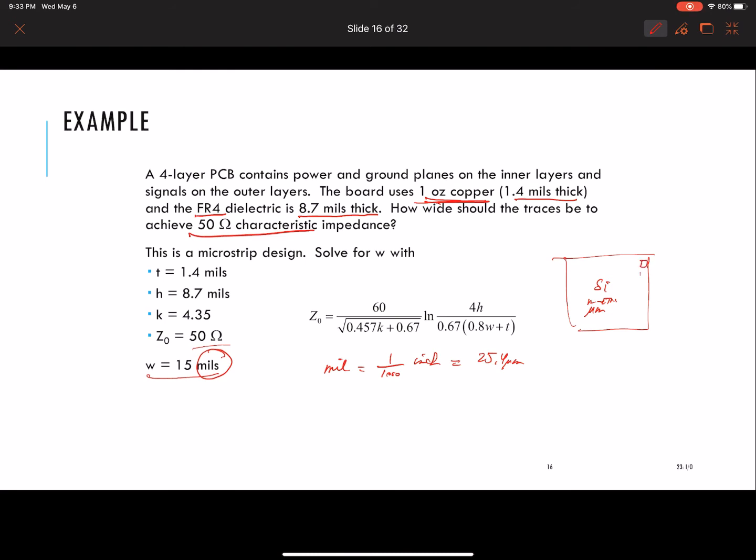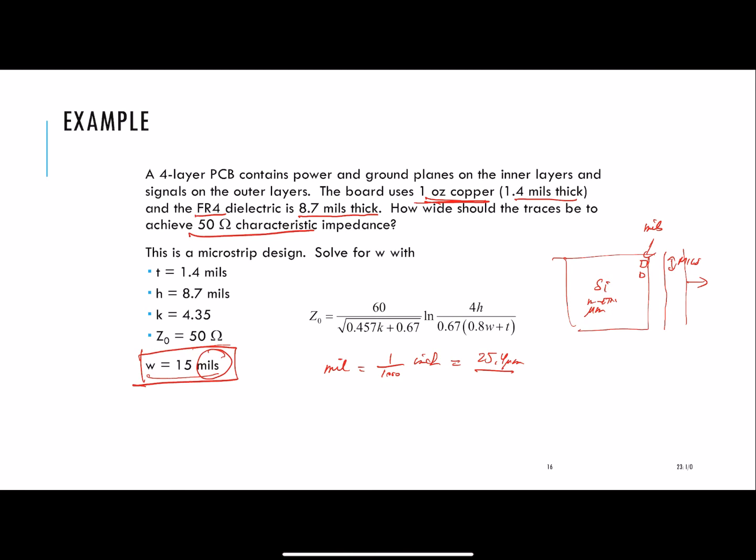When you get to the pad, you start talking about pad pitch and pad spacing in mils, because in the package people are talking about mils. And then everywhere else in the printed circuit board, everything is in terms of mils. For a long time I thought this was millimeters misspelled or something like that. It is not. It's a 1,000th of an inch, or 25.4 microns. No idea. Only in the U.S., I guess.